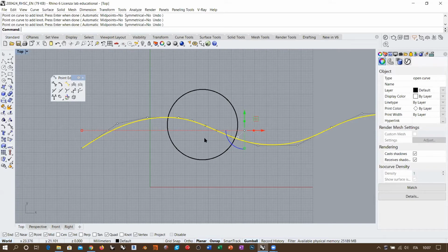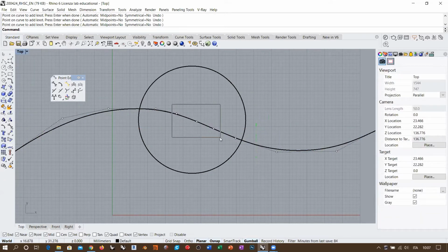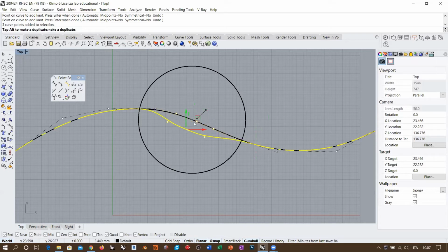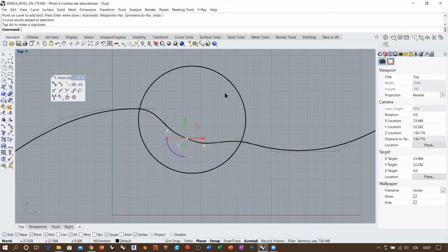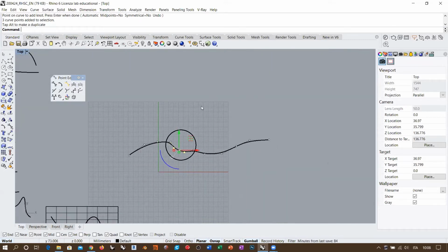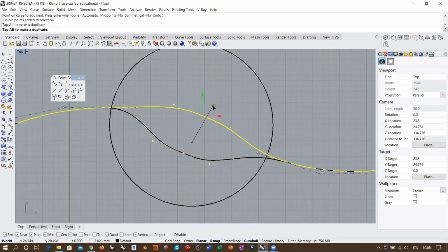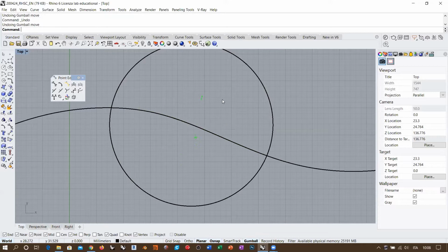So once I have added here a bunch of knots, I go back. The curve hasn't changed because the knots are simply topological division, and the control points are adapting to this new topological division. And I have this set of 3 control points in this area, which I can move around, and I get local deformability inside this circle. Okay. And if I want, I can align them, I can rotate them, I can scale them in order to have the same topological control as what we did here with the straight line. Okay. So you might want to work with adding knots and not control points, okay, if you want local deformability.